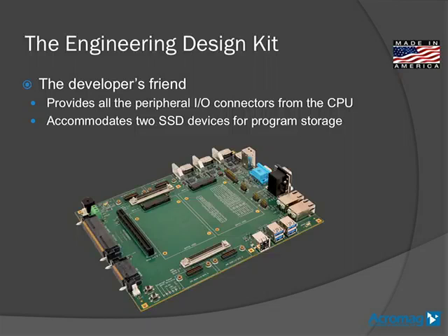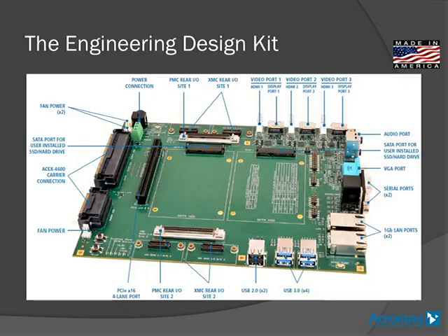The purpose of this board, and I'll go to the next slide, is to interconnect with the carrier card over here and the resident CPU, and whatever I/O you have on it. This interconnects to that, and then it gives you all your power connections, SATA ports. You have the PMC, XMC sites 1 and 2, depending on the configuration of the carrier board you're using. This EDK, Engineering Design Board, has all the outputs for that.